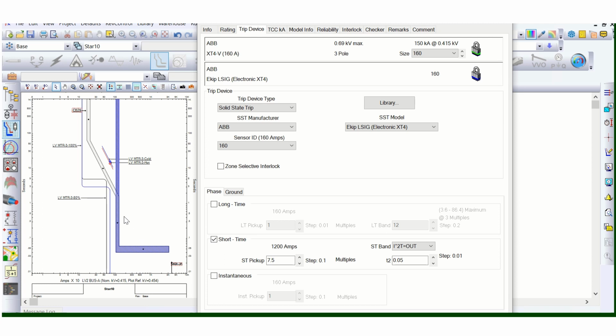This is basically providing the short circuit protection. So we are using the combination of these two, long time and short time, so that it is properly suited in between the motor starting curve and the hot thermal resistance curve, and it is protecting the motor from overcurrent or overloading and short circuit.